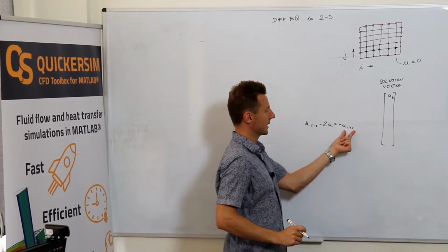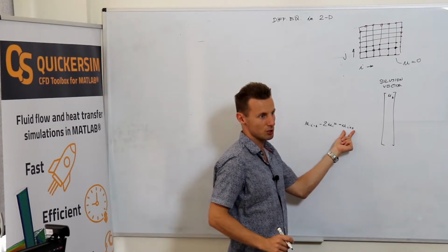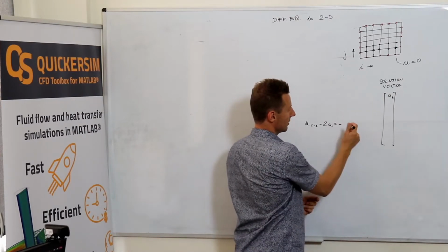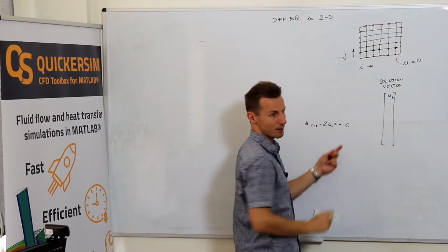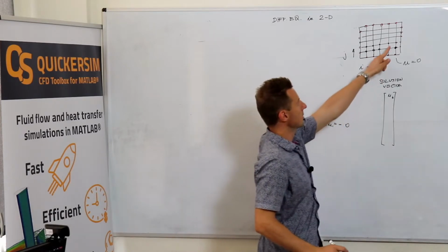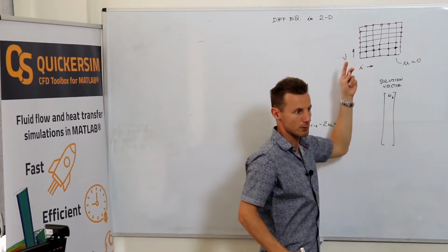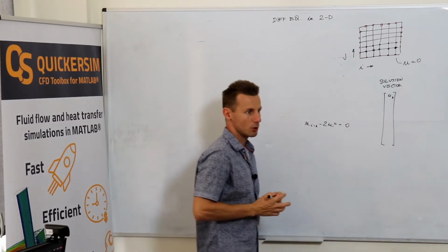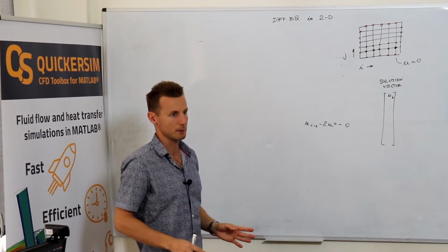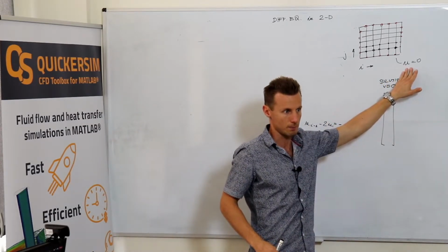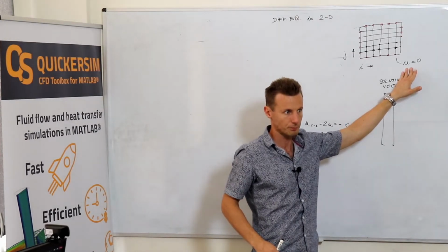But it doesn't exist. If you do not replace it by anything, it means that you've got 0 in your right-hand side vector. So using internal nodes and not using the boundary nodes at all means that you have automatically implemented the 0 Dirichlet boundary condition, right?